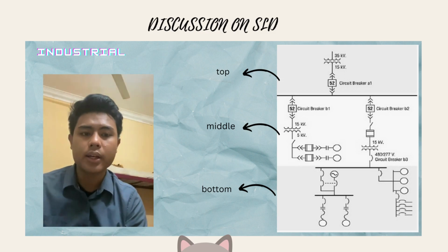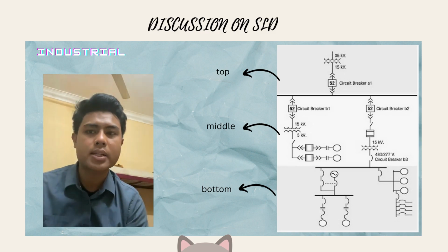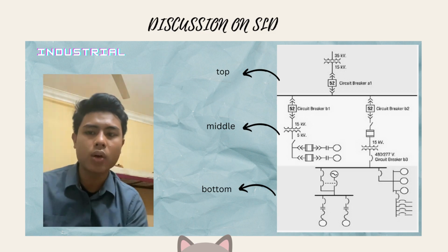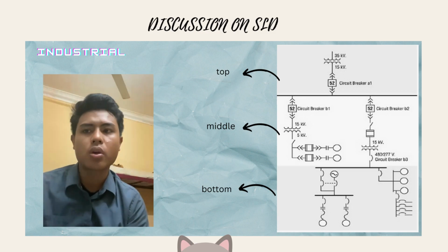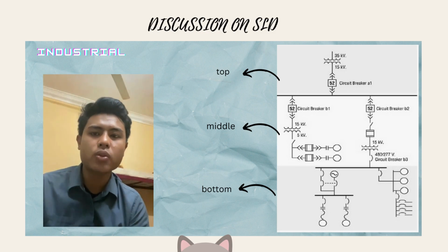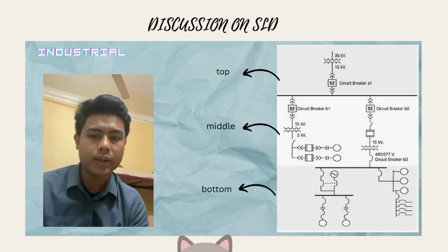Next, the single line diagram of industrial also provides the automatic transfer switch, marked as a circle in the single line diagram. It symbolizes the emergency generator. This section of the single line diagram shows us how crucial it is for the apparatus linked below the automatic transfer switch to continue working even when the power is lost. You can see from the single line graphic that if the power goes out, the automatic transfer switch would link the emergency generator into the circuit to keep the equipment working. Therefore, they keep the machinery operating. That's all from me for the single line diagram in industrial.